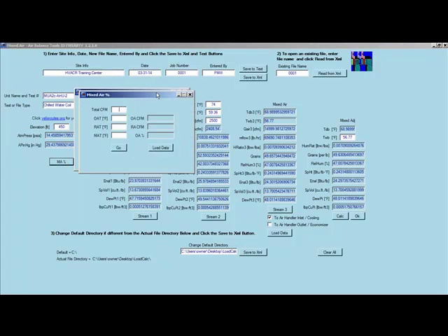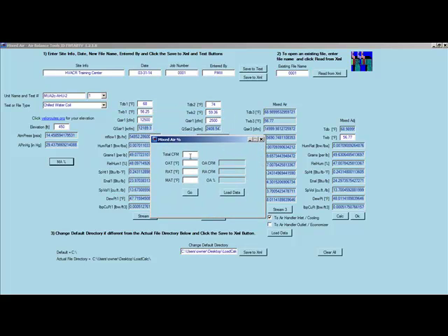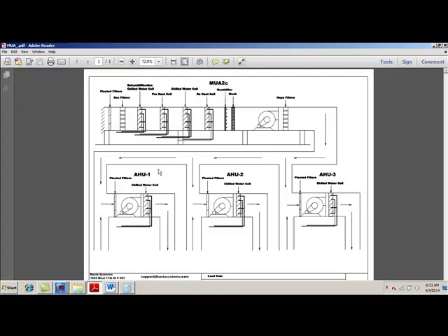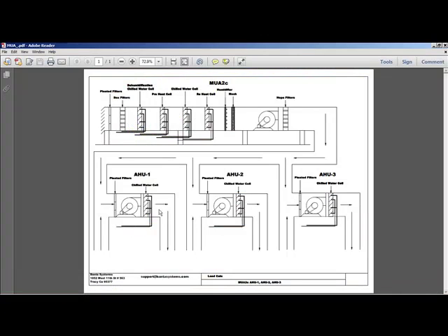So let's take a look at our mixed air temperature. And we'll say this machine also, for air handler 2, each one of them, we know what the outlet CFM is because these are rated. We've measured them, and we've got 15,000, 15,000, 15,000. In this very first one, we've already identified all our values. We're going to identify our mixed air from air handler 2, how many tons, how many GPM we're flowing through this pipe for the chilled water coil. So we have 68 at 48, 72 at 42.